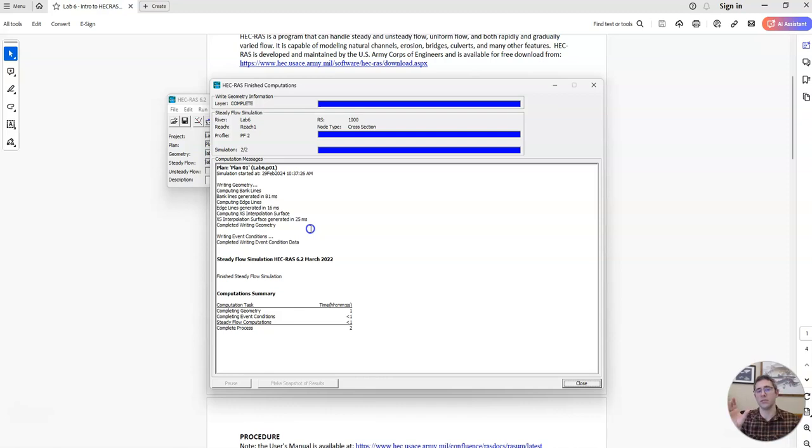And in the bridge editor, that the distance one is also correct, right? Distance from the upstream edge of the road to the cross-section upstream. Or that little table where we had station and then high chord. Those three things are sort of the most common. Everything has to be right in there for the model to run.